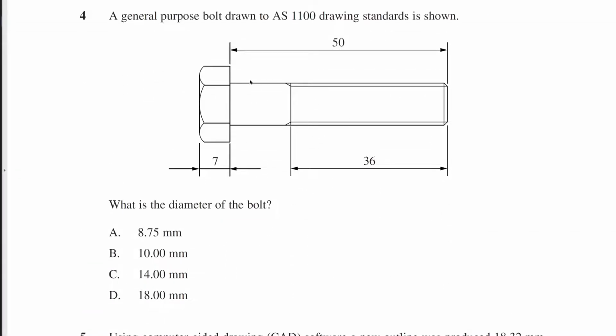So here we have a bolt. Now, once upon a time, I used to say to people, just learn the diagram on page 64 on the day of the exam. These days, I find that most students do remember head at 7, nut at 8. What that means is that the head of the bolt is 0.7 or 70% of the major diameter of the bolt. This is the major diameter.